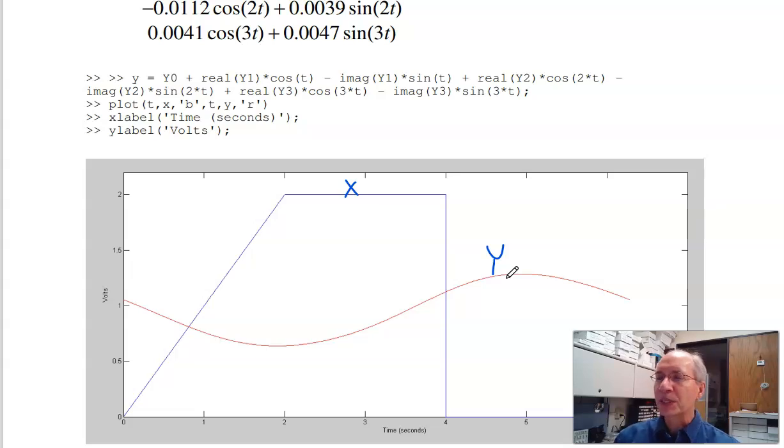You're going to need to use complex numbers, but if you don't mind complex numbers, it's pretty straightforward. Add them all up, I get the total answer. That's really the power. Any periodic input I can solve this way. And that's part of the reason that we're covering sine waves, phasors, superposition, because that really opens up what you can do. I can solve for any periodic input.